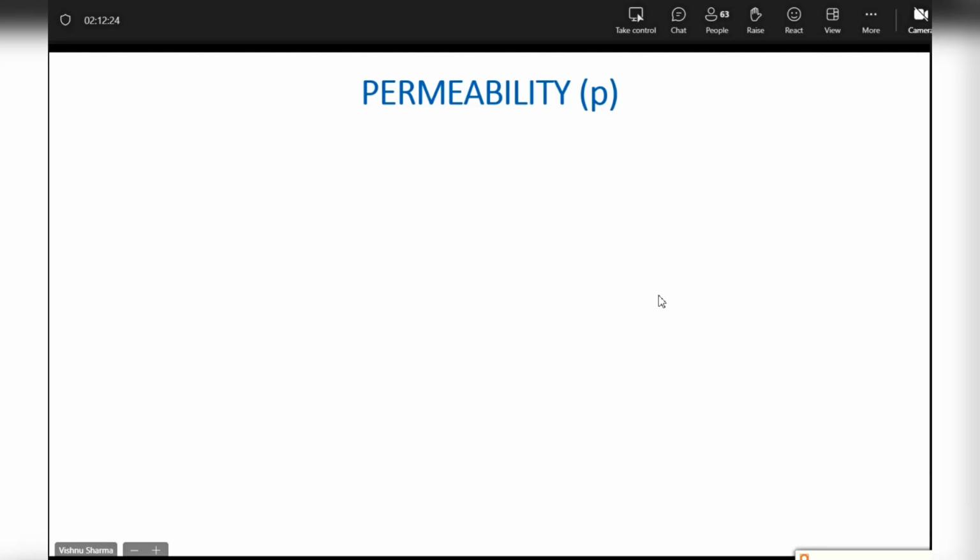So if the compartment is not empty and has some solid cargo or solid equipment or whatever, then that will reduce the ingress of water. Now, we are going to do our questions based on certain inherent assumptions, because if we do not have inherent assumptions, then we'll have to have complete details of a case. So our generic calculations will be based on certain inherent assumptions.